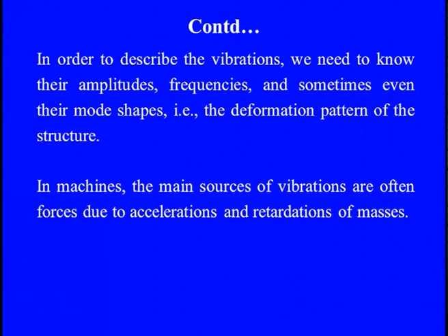Because as we discussed in the previous part, when we talk about the first natural frequency or second or any degrees of freedom natural frequency, we need to check the relative position of their masses, and this simply tells you how dangerous it is, because there are various modes coming out from that. Maybe we have axial mode, maybe shear mode, maybe bending mode. Various modes are straightaway reflected in these natural frequencies. So here we need to compute not only the amplitude and the frequency, but also the deformation pattern of the structure.